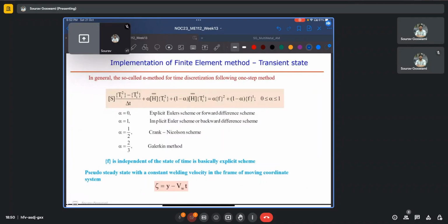So we would have to perform discretization of the solution domain, both in the spatial frame as well as the temporal frame. We have already divided the region of interest, say a 2D surface or a 3D volume, into finite space steps, say into very infinitesimal cubes, or in the case of surfaces, infinitesimal areas, or in the case of lengths, into infinitesimally small elements. And then later in the temporal space, we also have to break them into time increments.